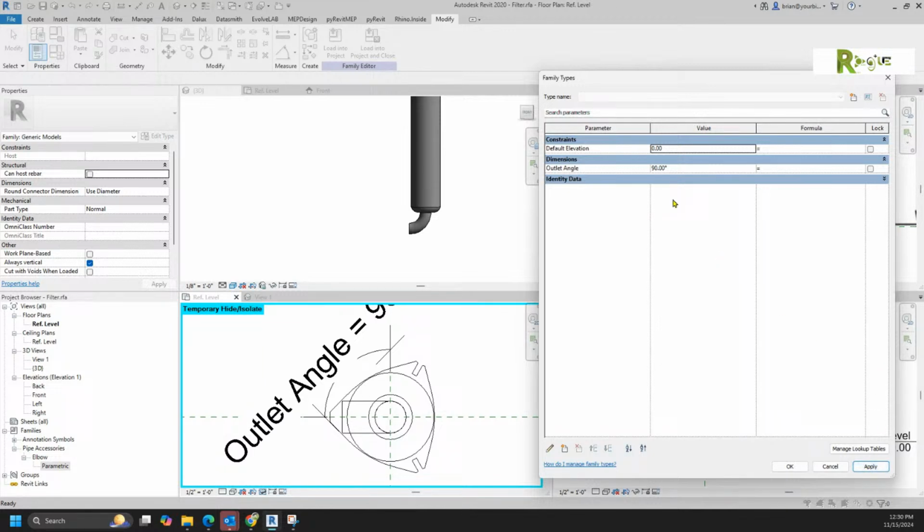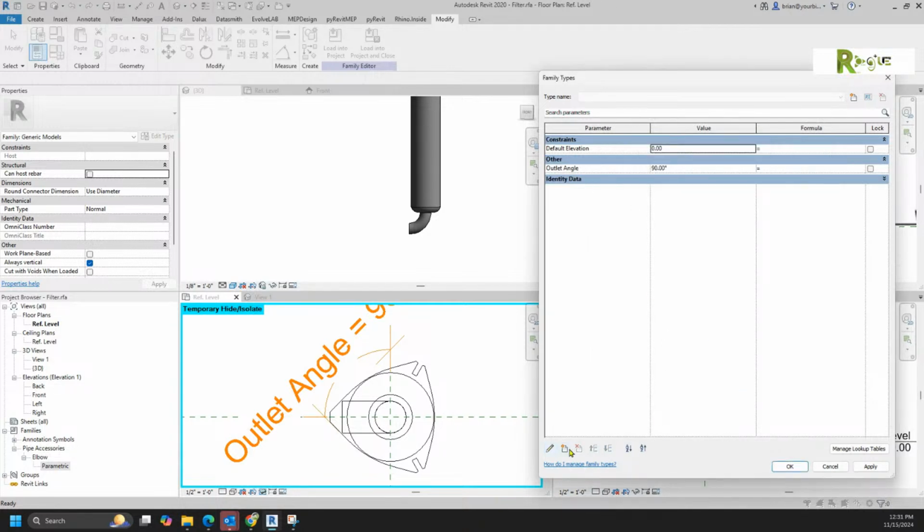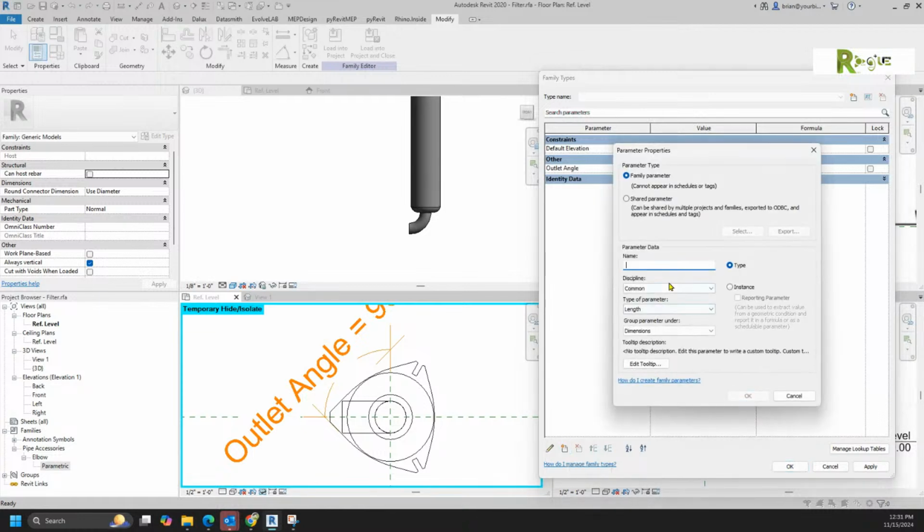So now what we do is that outlet angle, because to me, that's not a parameter someone should be really messing with. I'm going to move that parameter down into what's the other. Sometimes I put them in construction if I really want people to change them. But what we're going to do now is we're going to make a new parameter. And it's going to be flip outlet. Okay. That's going to be an instance parameter. I'm going to throw that as a yes, no.